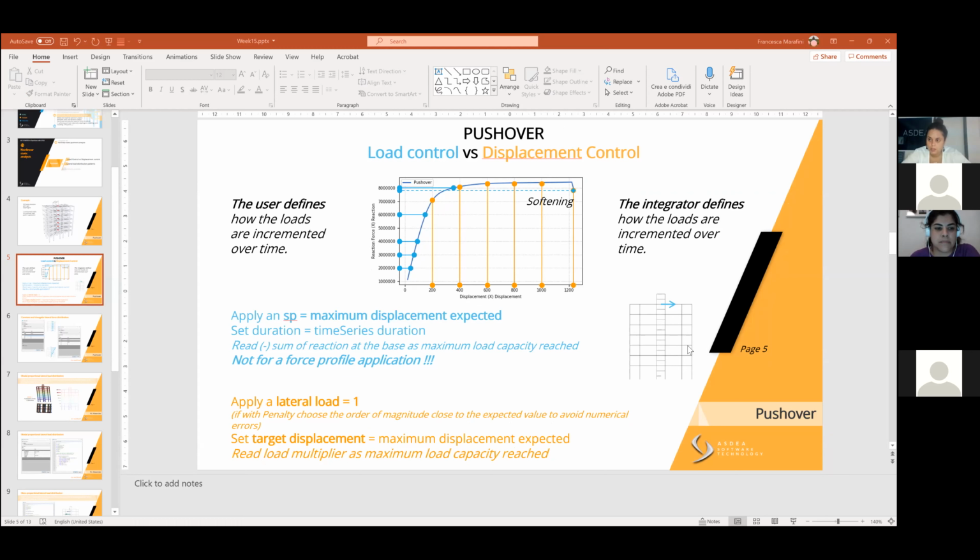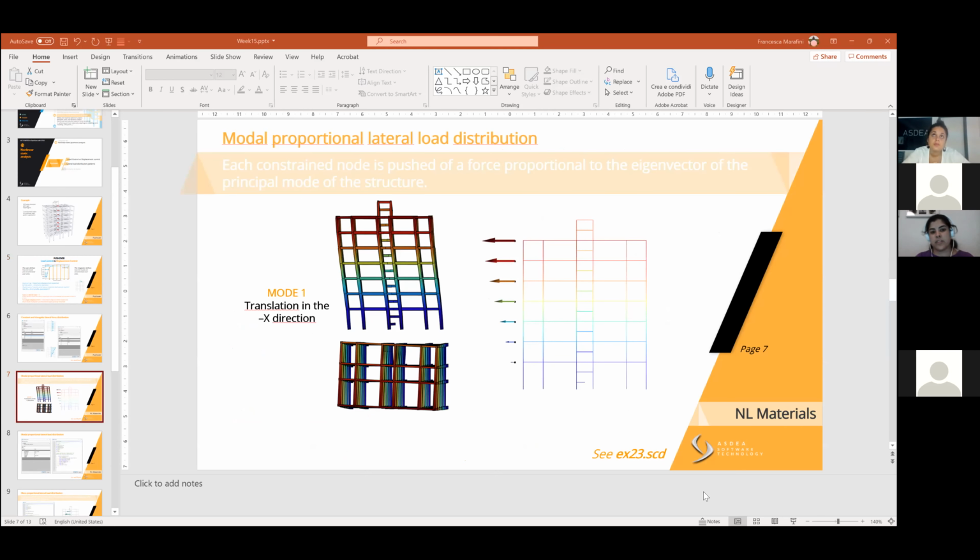Because, for example, in slide 7, in this case, because your structure is not completely symmetrical, this horizontal displacement in X actually has a bit of rotation. Yes. So sometimes I think that if I put maximum, I won't actually know which is the node that is actually moving. I would have to go one by one, plotting to see which one moves. Okay, but what you can do is, for example, let me take the file.